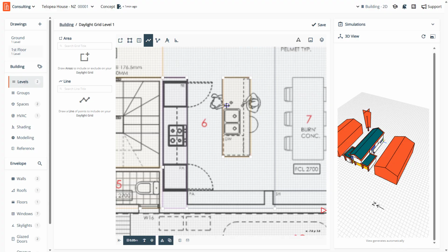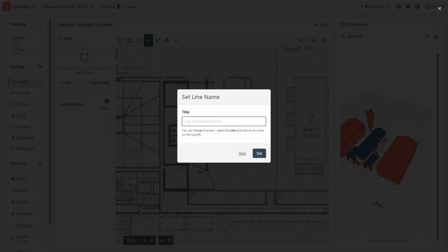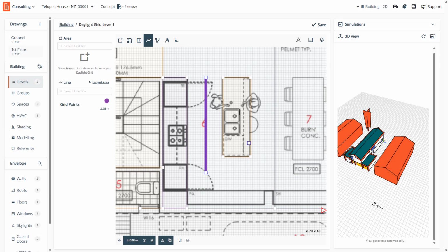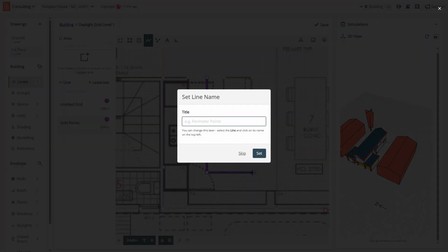So there is a rule set in G7 that in this case you must draw a set of grid points. Once you draw these grid points, we're going to be able to extract results from the length of this grid point here. So all I've done there is select add lines and do it like that, and I'm going to call this grid points 2.